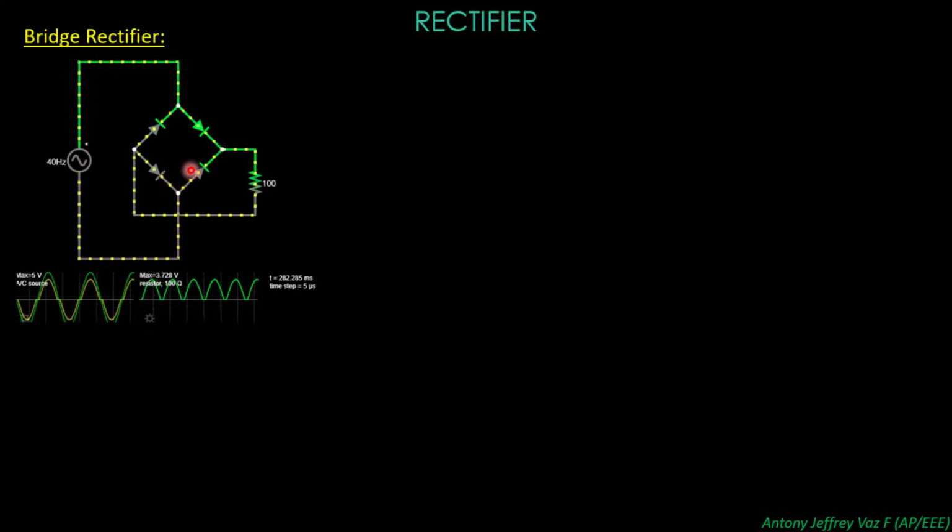There will be 4 diodes, and one end of the bridge, that is the negative and the positive end of a diode, is connected to the AC source, and the other negative and positive end of the diode is connected to the other end of the AC source. And similarly, here you can see the two N junctions of the diodes are connected to the resistance, and similarly the two P junctions of the diodes are connected to the other end of the resistance. So the bridge rectifier has a very simple circuit.